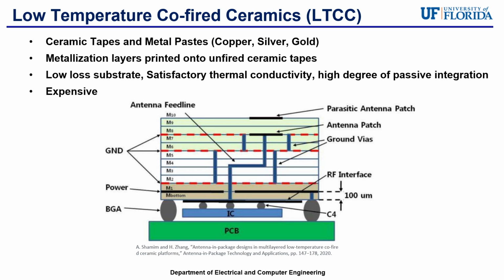Because of this, there is a low loss of substrate, quite satisfactory thermal conductivity, and a high degree of passive integration. However, the entire fabrication process is very expensive. The figure below showcases a 60 gigahertz LTCC based patch antenna array and is the side view of the AiP